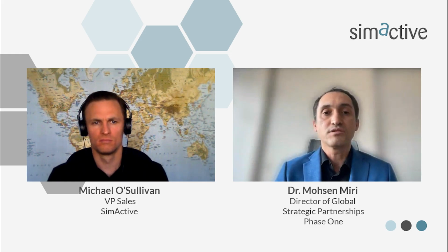But if you're going to fly over a city, dense areas, and you need really high accuracy and reliable geometry in your block, you should think about well-distributed ground control points, right? And it is always important to consider the customer's request, and how they will validate and qualify the accuracy and precision of the project. I think it's very important.